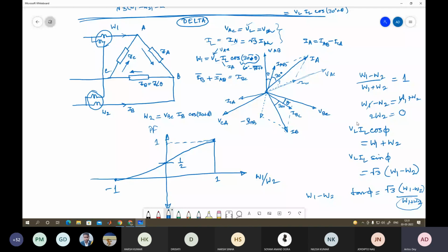So whenever the angle between some line current and some line voltage is more than 90, if you just change the polarity of voltage, then it will be less than 90. Like if it is 120, then if you change the polarity, it will be 60 degrees only. Or if it is 110, then it is 70 degrees. In that way you'll be able to find the wattmeter reading, which you can measure using the meter, and then you should put the sign as negative.